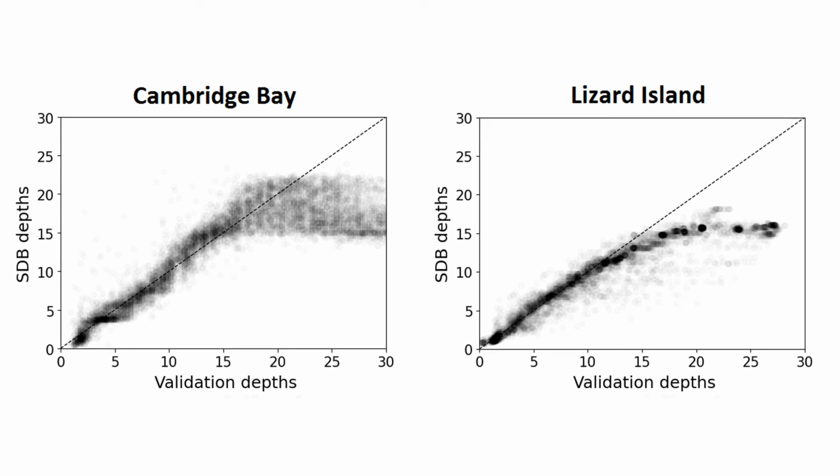of the 90% confidence intervals, and we set a threshold that eliminates all data beyond the depth that corresponds to a given interval. An example is shown here. Confidence interval ranges are shown with red arrows, and a threshold that eliminates all data from depths where the confidence interval range is greater than 3 meters is shown with a horizontal red line. Other approaches exist to masking out optically deep water, and we're always looking to further refine this work.